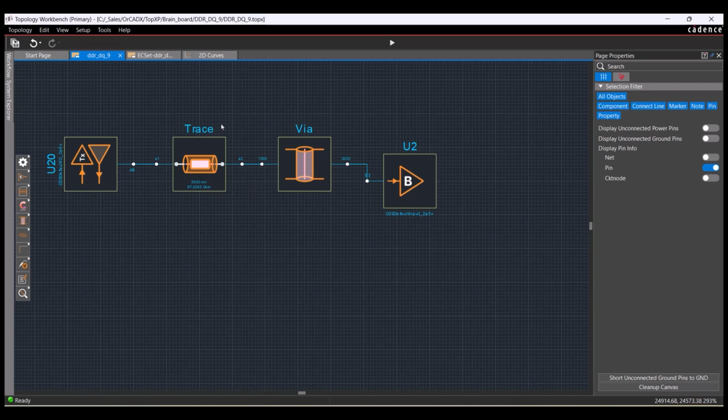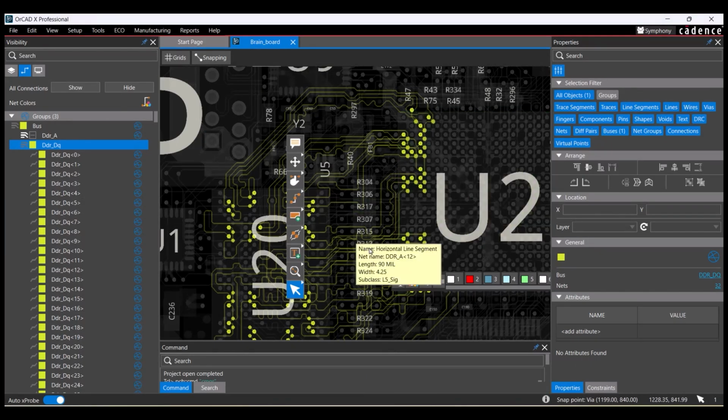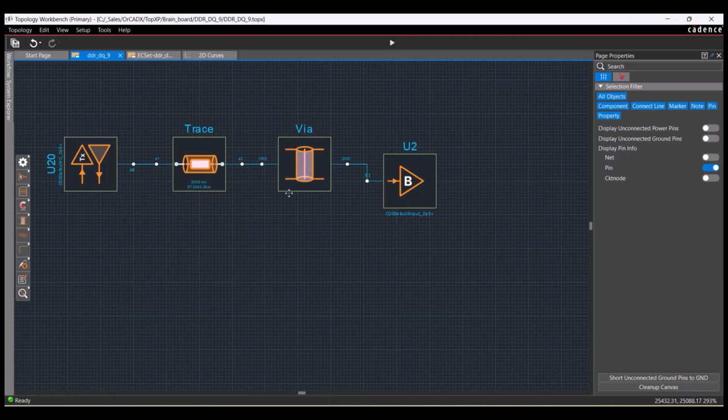Once you get all of this refined, you would then switch the tool over to the constraint entry mode. So again, you can use this tool in one of two ways. You can either use it after you've done your layout to extract what's been laid out and run an analysis to verify constraints, or you could do it before you have even laid out anything in the design. All you need is the net list, and then you're using it to determine what that interconnect should be and create a constraint.